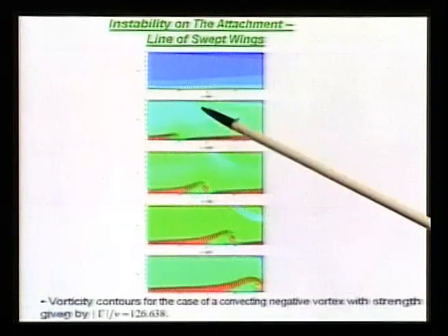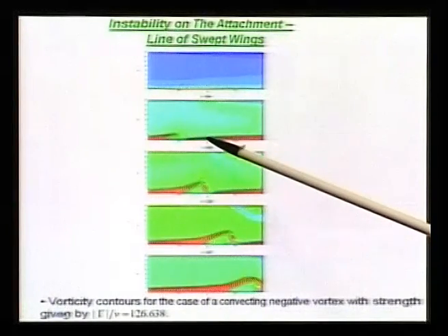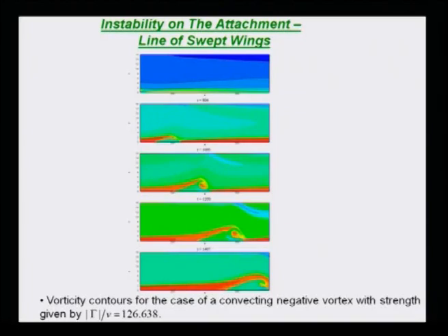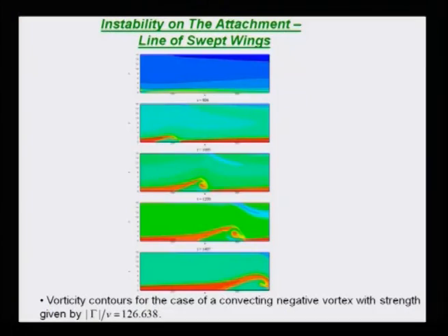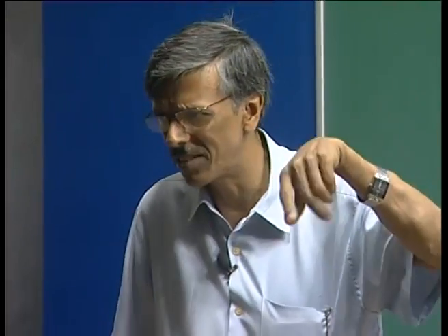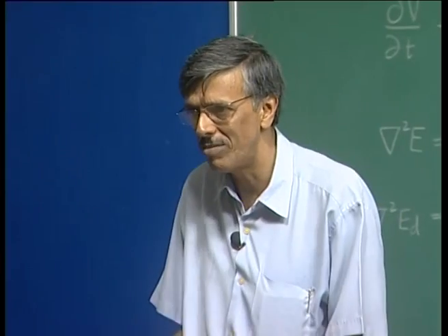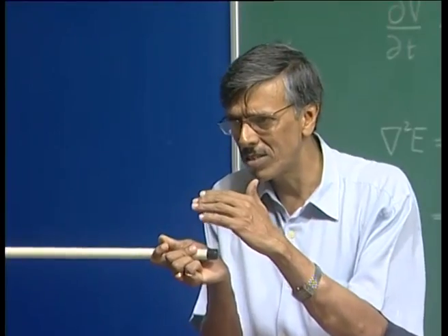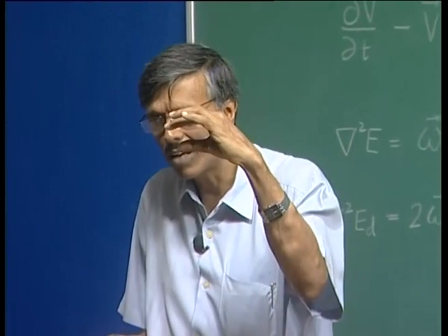So, you can reason out that the vortex must be here, and then you can also see just ahead of the vortex the boundary layer thins down. So, you can see the vortex must be exactly on top of this. That is why you do not need to even provide the arrow. As it goes along, we have noted from that sketch, recall the flow past a rotating and translating cylinder, we saw how the streamline converges and diverges. For this case, the streamline diverges just behind the vortex, but again if you go a little further down, the streamlines are narrowed down.